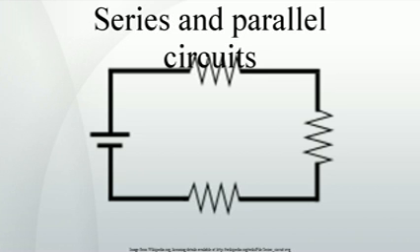Inductors. Inductors follow the same law, in that the total inductance of non-coupled inductors in series is equal to the sum of their individual inductances. However, in some situations it is difficult to prevent adjacent inductors from influencing each other, as the magnetic field of one device couples with the windings of its neighbors.